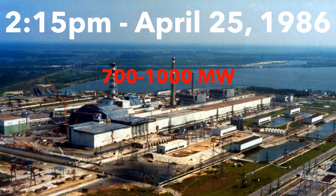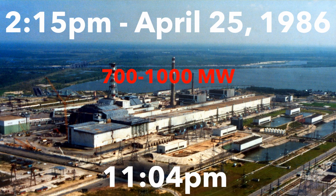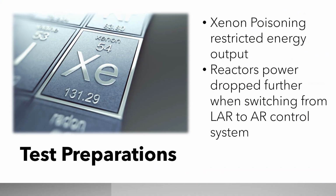When the test was allowed to begin again, the night crew, who was not trained for this test at all, had started their shifts at 11:04 p.m. However, due to a phenomenon called xenon poisoning, the reactor was only producing 500 megawatts. They then decided to switch the reactor power control from local automatic regulator to automatic regulators, which gave them manual control over the power level. This would then result in the power output reaching 30 megawatts, near shutdown levels.